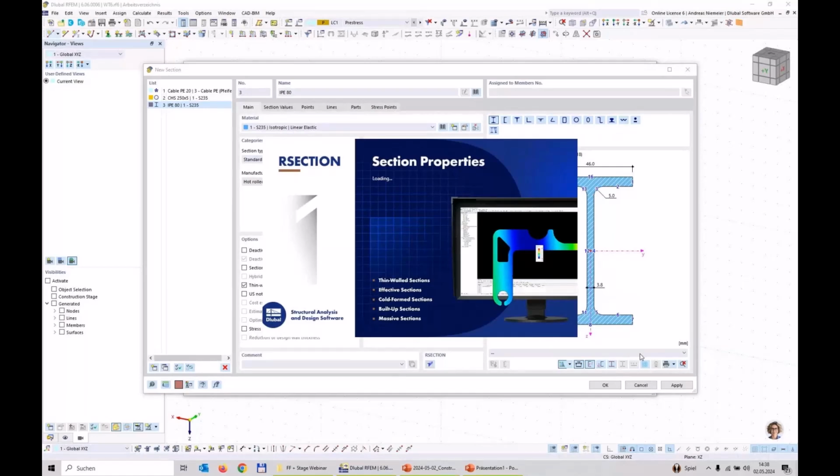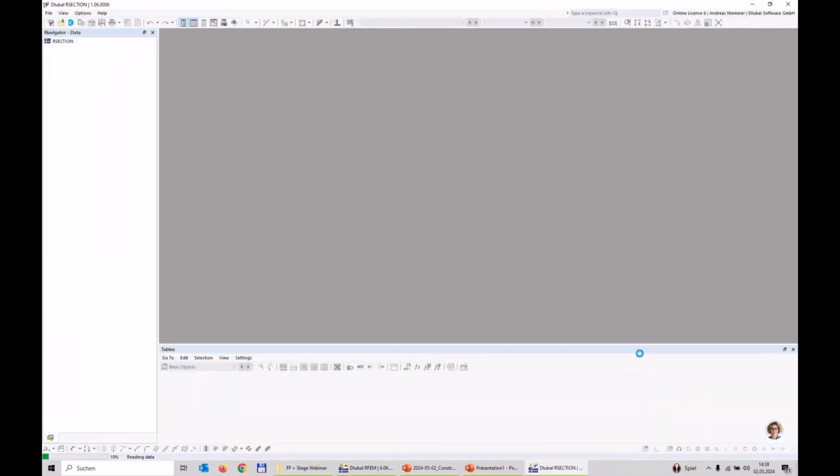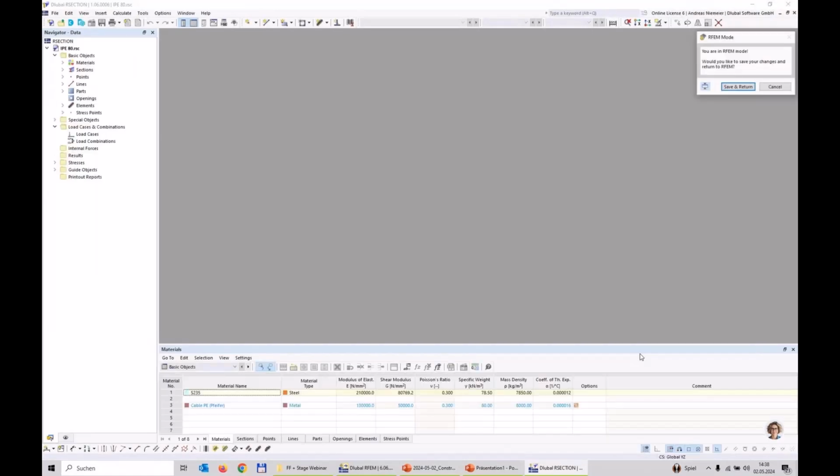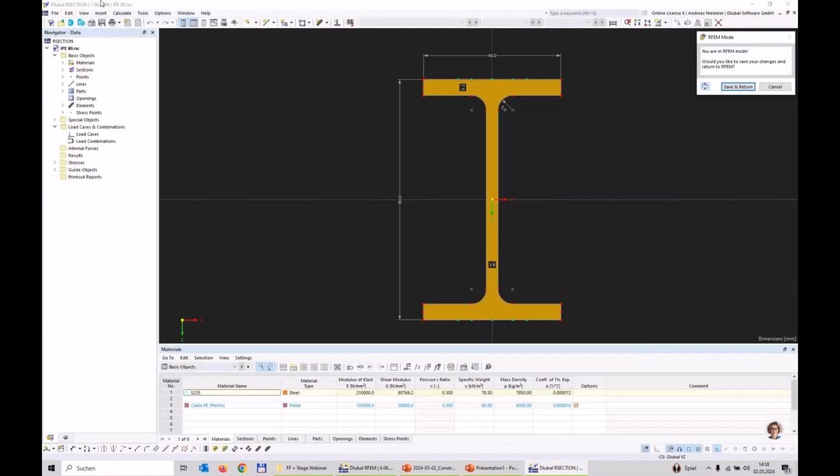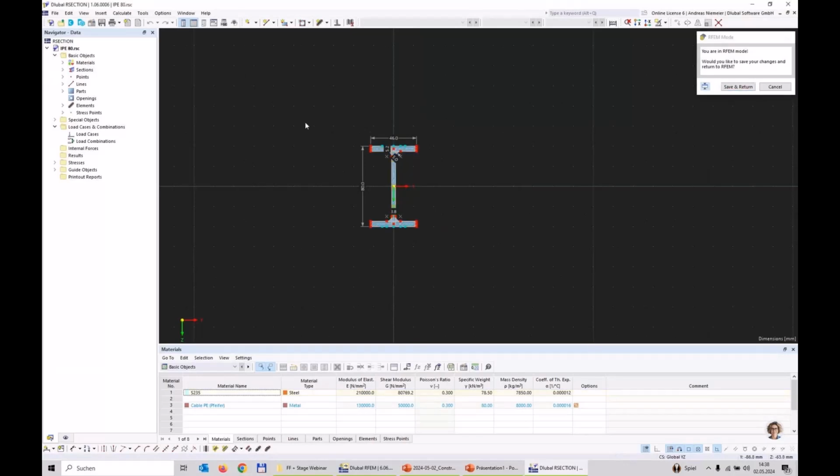This triangle cross section that I mentioned, the hollow section from triangle shape, not the circular, a triangle hollow section. So the program opens a section live from RFEM, which allows us to model here a user-defined section in time. So this was the standard settings, this IPE80, so we can delete it.